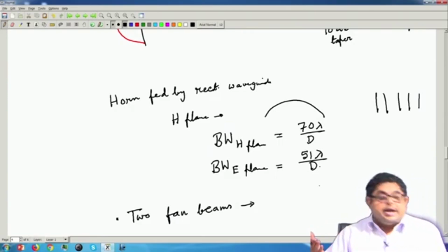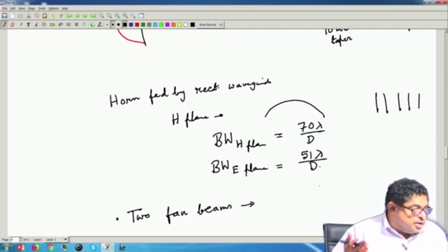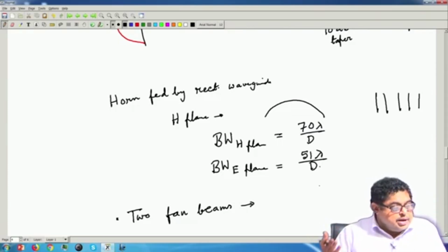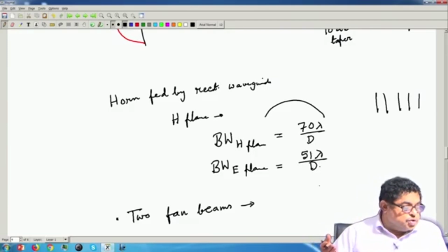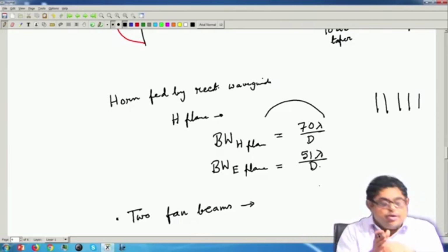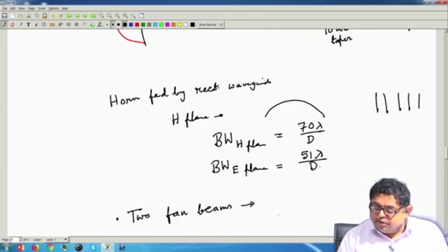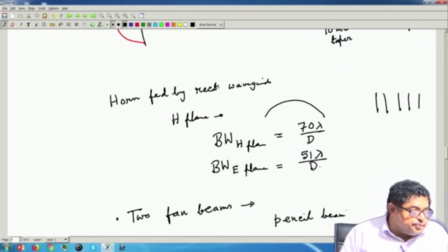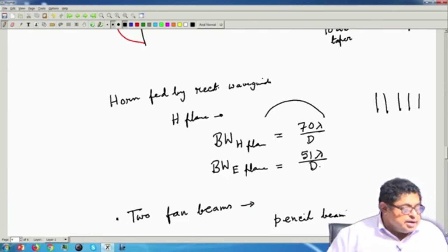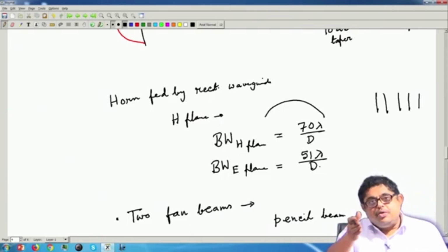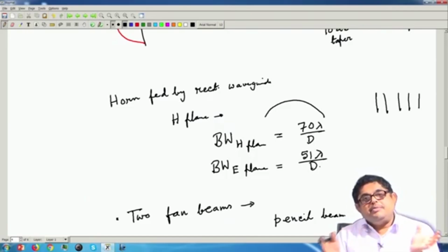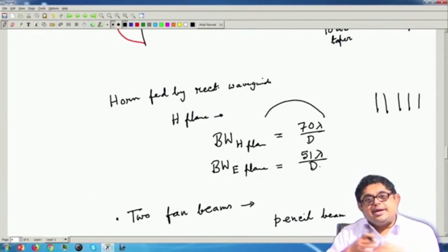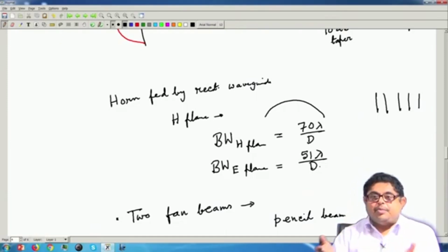On the other hand, suppose a weather radar on a plane locates storms only in the plane's path. It can use a narrow beam; in radar parlance, narrow beams are called pencil beams. So, a weather radar can have a pencil beam for searching, and it can also go on tracking. Once you have a pencil beam, you are basically doing it like a tracking radar. So, the same beam can do both search and track operations.